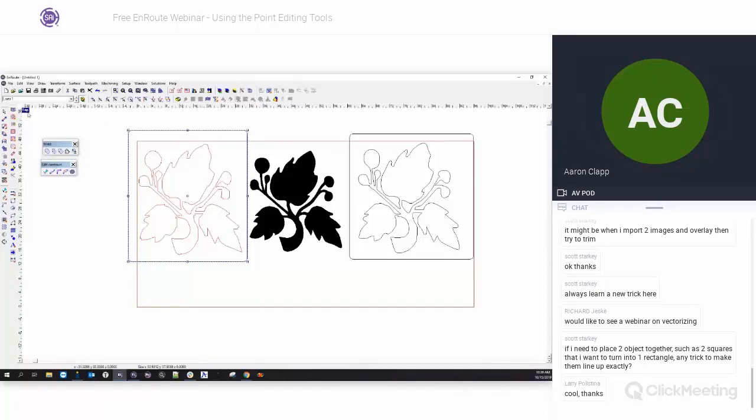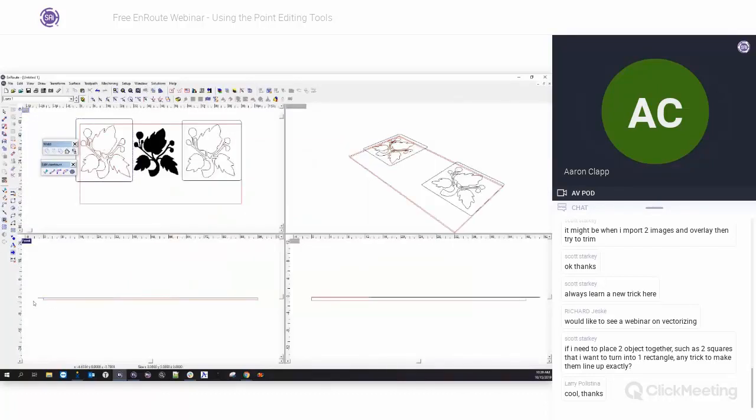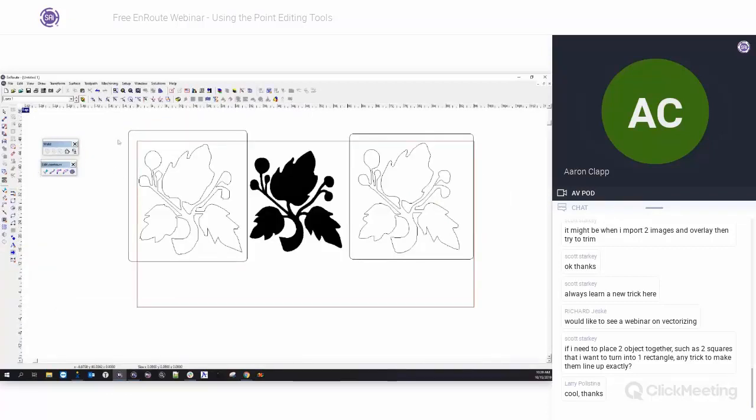This is a little bit less common, but you can also go into the side view. Sometimes what will happen is you may have duplicate lines on top of each other, but they may be on different z-axis. So you might have a line that's maybe farther down in the z. So sometimes checking the side view might give you a little bit of an indication of what's going on. That's not as common of a one, but it's also another thing to check. So those are the three things that I usually use. I use my highlight, I look at my side view, and then I turn on my show intersecting contours, and those usually tell me more often than not if we have an issue.